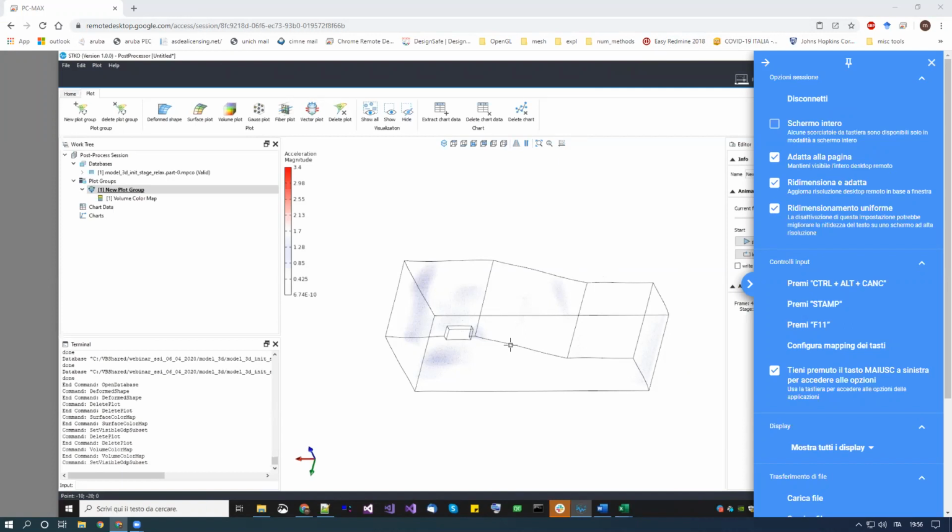But actually, that is not a problem because the zero length element does not take into account the physical length. I just made them distant because it was easier for me to select the different pieces. If you want, you can move those pieces together, and the zero length will have an actual zero length. Instead, if I used the two-node link, it would have created some problem because the two-node link takes into account the distance, because it couples displacement and rotation. So don't use two-node links in these cases. Always use a zero length.